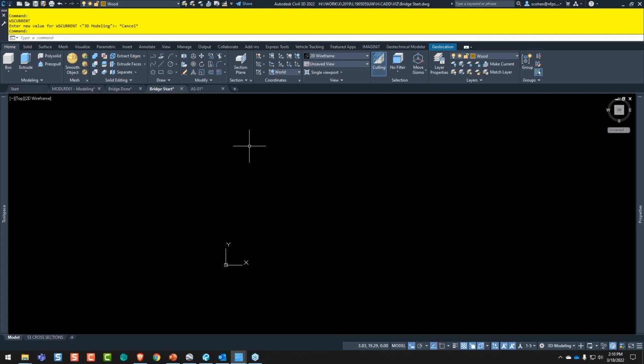Now, one thing also to mention is if you want to automate the rendering, what you could do is have a template that has layers. I made this really simple so you guys wouldn't get overwhelmed with layers. I've got about 6 layers here. 1 layer for each object type that I want to automate the rendering for. I have a concrete foundation, the concrete posts, fences. I have a miscellaneous layer in case you want to just draw something in CAD, a roof, and a wood layer. All right, so these are all mapped already.